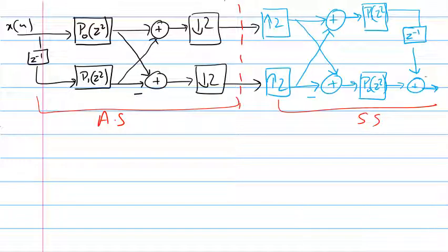This is your x̂(n). So using those two pairs of equations which I showed you, we can implement the quadrature mirror filter bank like this. Basically we have realized the filters in this way. You can see a delay element is used, and addition and subtraction as per those two equations which I showed on the previous slide.